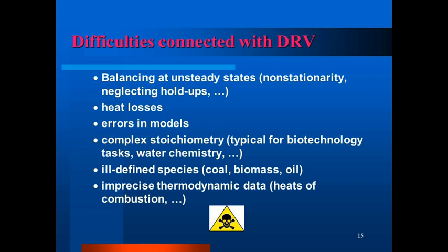There can be also changing inventories like tanks between process units. Recon is capable of dealing with such cases. We talk about so-called dynamic balancing. We can also meet heat losses to the environment in the case of heat and energy balancing. In some cases, when the equipment is thermally isolated, heat losses can be neglected. In other cases, the heat loss should be estimated and included in the balance.